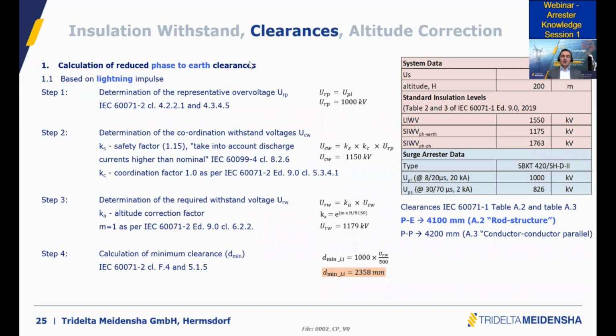For installation at higher altitudes, the manufacturer of the circuit breakers, bushings, or surge arresters should confirm the performance at the required altitudes. If not, they have to use longer housing, right?